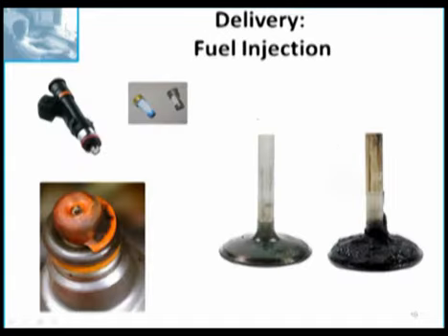Also, when we think about the fuel injectors, we have to consider the effect of deposits both on the tip of the injector and deposits on the intake valve. And these deposits can cause a dilution type of a lean condition. The good news is it's going to almost always happen at idle. And to eliminate this one, you bring the engine off idle and watch your fuel trim. If the fuel trim gets a lot better as soon as you bring it off idle, you're clearly dealing with a dilution issue.